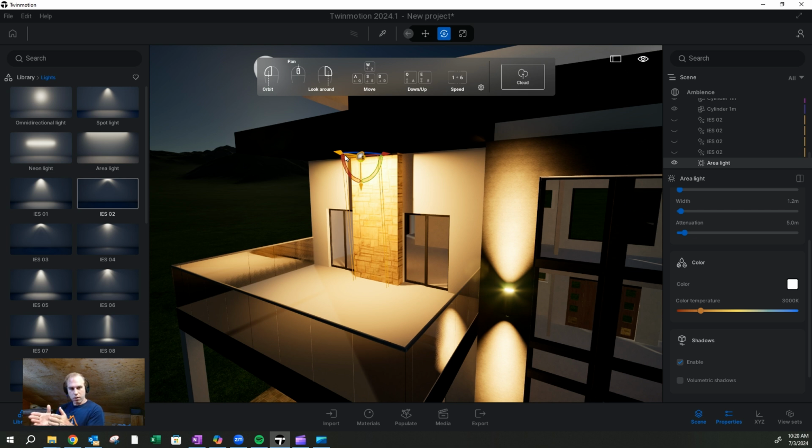It works the same way. So if you have narrow optics, you're actually getting more functional light to the ground, to the point that you're aiming your water spigot, your light fixture, at. Versus if there's no optics, you're losing 90% of your light output in the first 3 to 4 feet. That's why sometimes when you see these $4 million homes being lit with these $9 wafer lights in a 14-foot ceiling, it takes about 1 million of them to get the actual light that you need down to the ground, and it doesn't look very good.